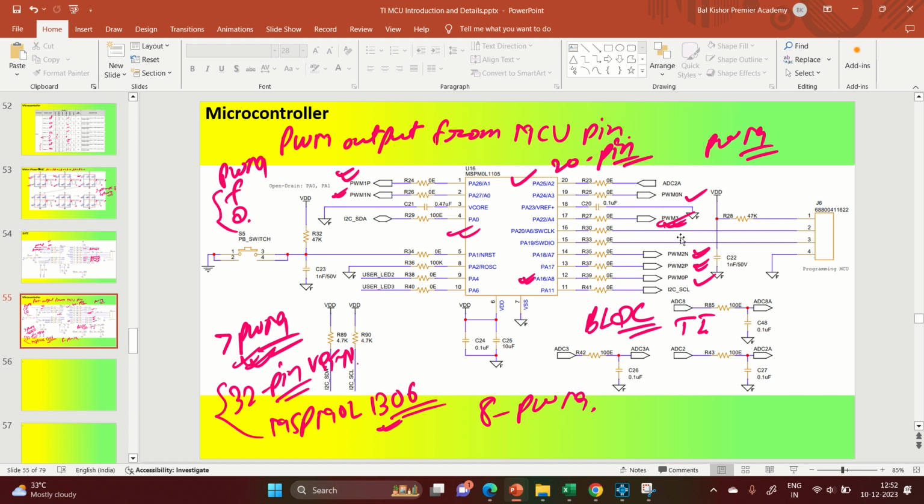So these are basically used for either dimming the light, so this will be used in your LED driver or something. At the same time, reducing the current through the motor. So motor current, if you want to reduce, there will be a pin where you need to have PWM input, which will help you to reduce or increase the current output. So for that purpose, this single PWM will be utilized. Okay, so if you are going to use only one PWM, this microcontroller is best suitable.